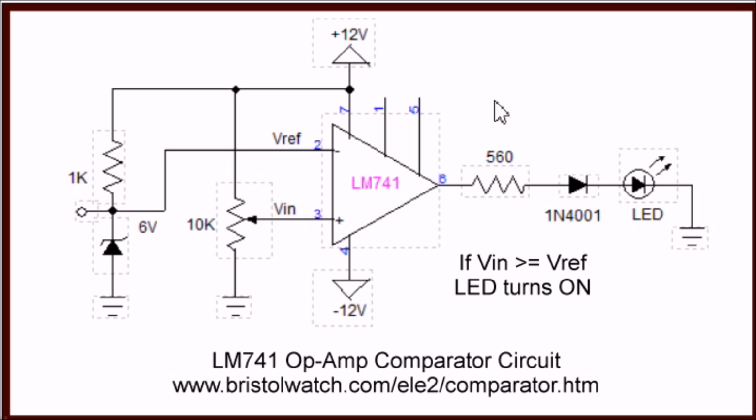It switches from plus 12 to minus 12, and it would have reverse biased the diode LED and could have damaged it. So that's what this is for. So as far as that goes, like I said, when Vn exceeds V reference, the LED will cut on. But it's a real headache with these bipolar devices, because a lot of times you don't have a minus 12 volt supply hanging around. Let's look at how to get around that problem.